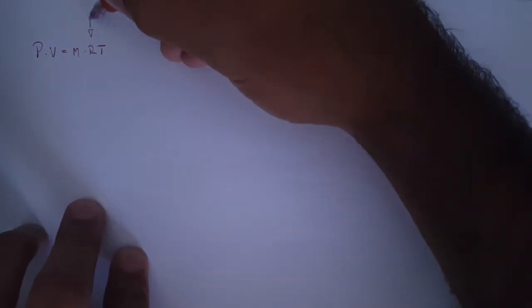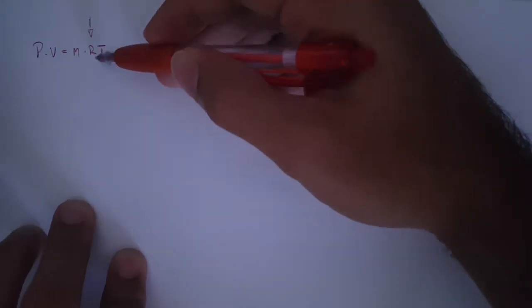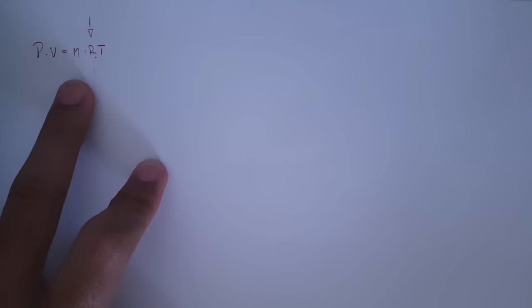All right, so continuing here, our quest to find the mass in this gas. There's two options. I'm going to give you the easiest one. I'm pretty sure you're not going to like the other one. Our options are, we can use a general R, the general constant, which is going to give us a number of moles. We can grab the number of moles with that constant. Or we can use a specific one for hydrogen and grab the mass straight off the bat.